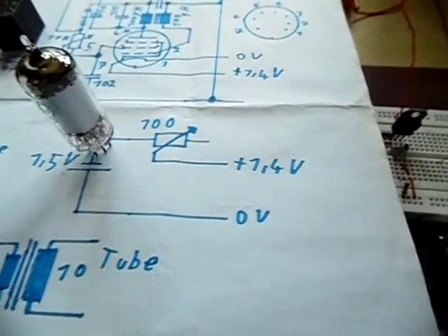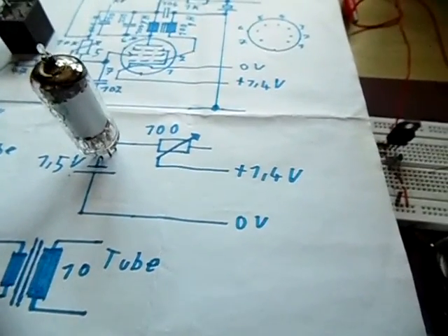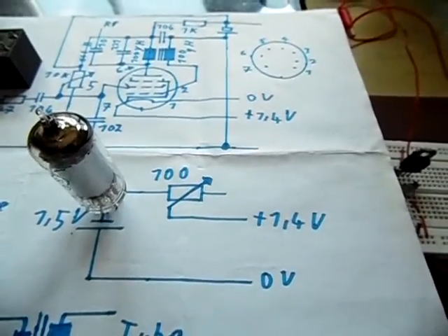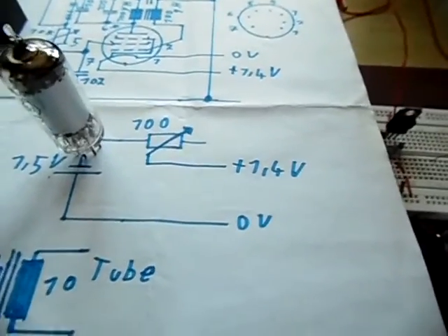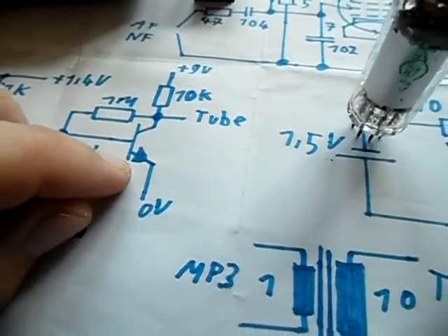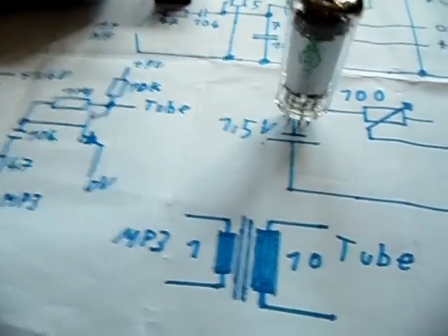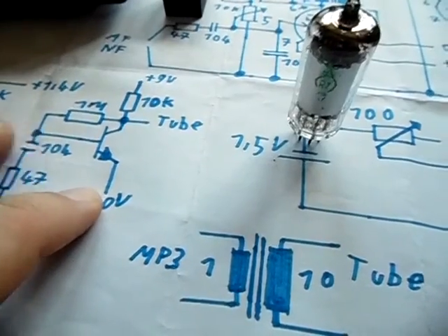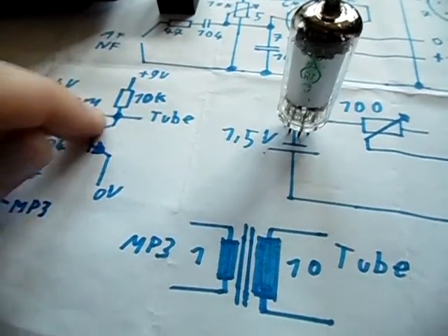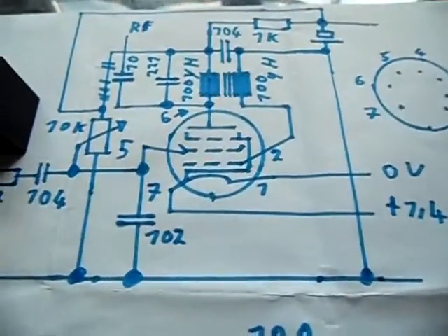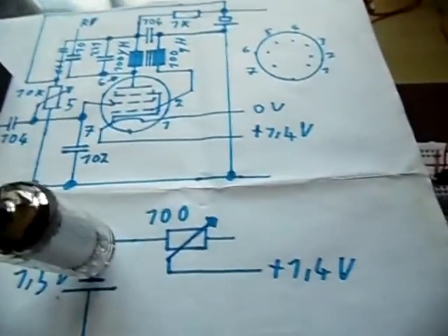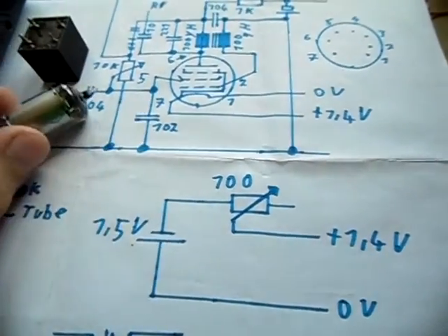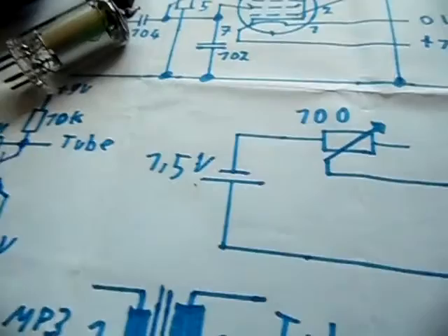It is said that a tube can be compared with a transistor. But I made this comparison, and it's definitely not that. Because on a transistor you have your emitter and your collector and your base. And if you add a signal between emitter and base, a positive signal on base, it will get conductive between emitter and collector. But a tube is another story, a very, very different story, because you have so-called grids. Grids are compared with a transistor's base, but they are something completely different.